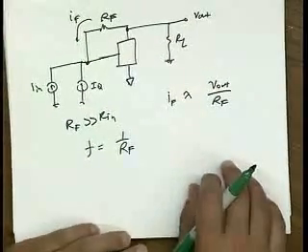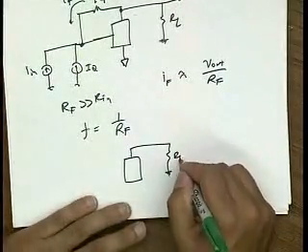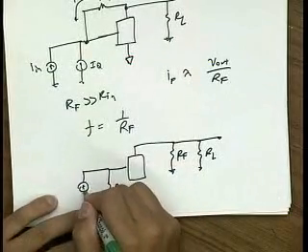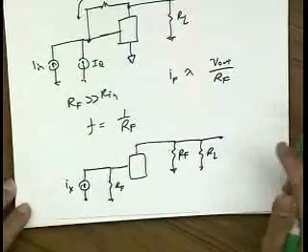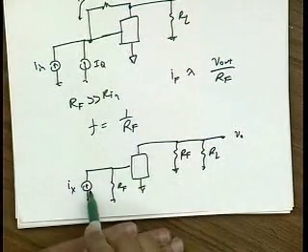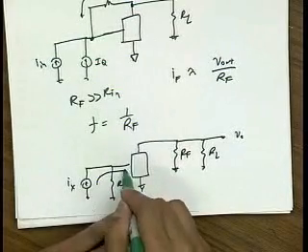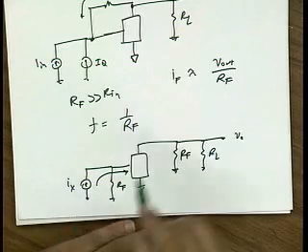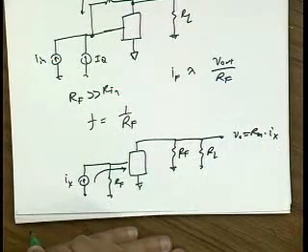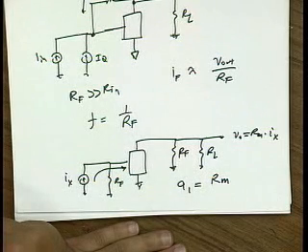Okay, well, what's the forward gain? Well, the forward gain is basically we break the amplifier and include the loading. We apply an input signal, let's say Ix, and we find the output voltage. Now, because the input impedance is very low, almost all the current is going to flow into our amplifier, right? In fact, you're told that RF is much bigger than the input. So that means that all of Ix goes into the amplifier, and the output voltage, therefore, is just Rm times Ix, which means the forward gain of the amplifier is Rm. Any questions?